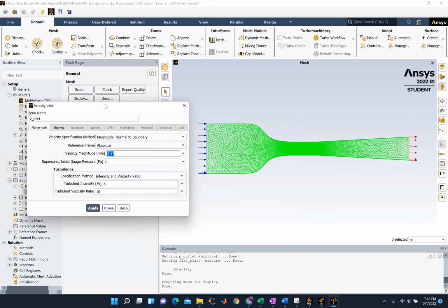So for this case, we're working with 50 hertz, which means that our test section target velocity should be around 12.07. And then in order to do so, we use our height ratio of 6 inches to 22 inches to backtrack and get this as our inlet velocity. It's just something that you play around with to try and match the conditions as much as possible. So I found this to be a really good match in my scenario.